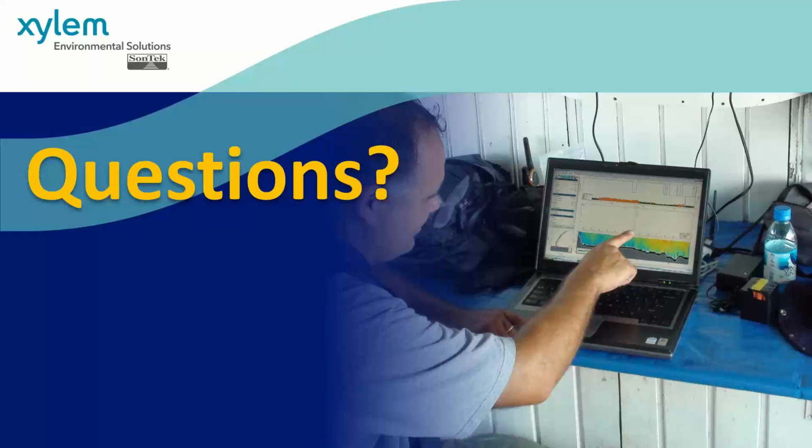But oftentimes this isn't available at specific sites, whether it's because your region hasn't set up a service like this, or your network RTK base station is too far away, so you're going to have large enough errors to not make this worthwhile. You will want to have a physical base station, so you have your rover and base station pair in order to get your RTK accuracy there.